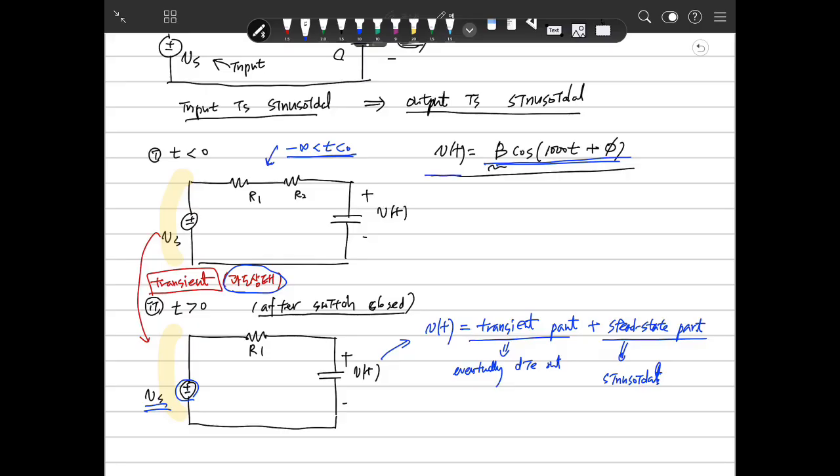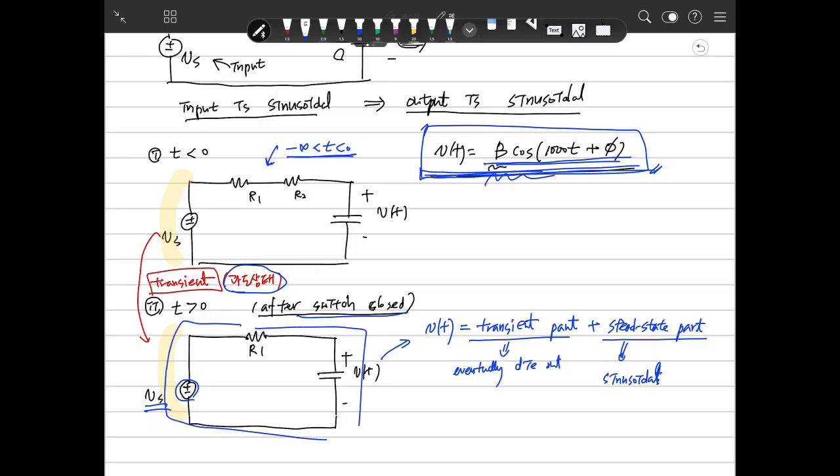So the reason we know this circuit solution is that we don't need exactly their values. The reason to redefine that value is to get an initial condition. When the switch is closed, there is a dramatic change in the circuit. Then we want to know what the initial condition of this circuit is. So in this case, we need to know the initial condition over here. In the case of a capacitor, we should know V(t) at 0 plus.